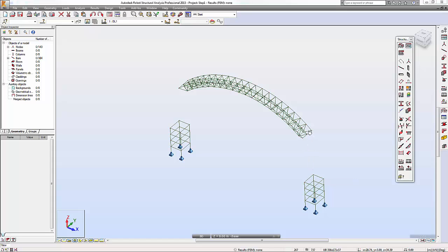Like if you have x, y, and z displacements, they link these two together, so as to tie up these two. So when this node is moving along this direction, the other node is going to move together with it, so you can set up all this information and force these two to deform together.